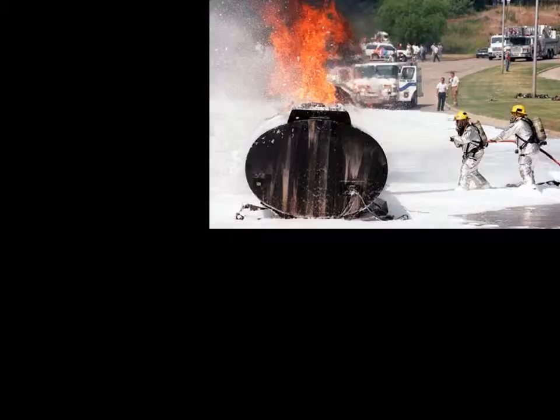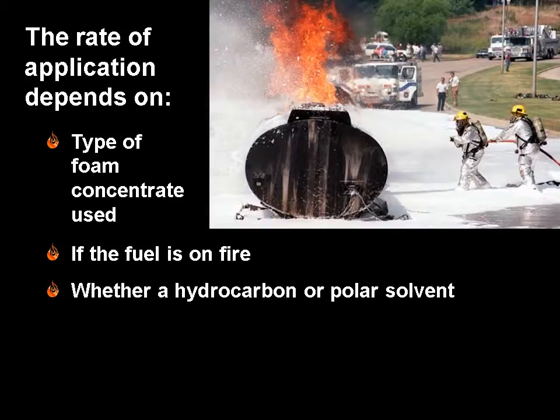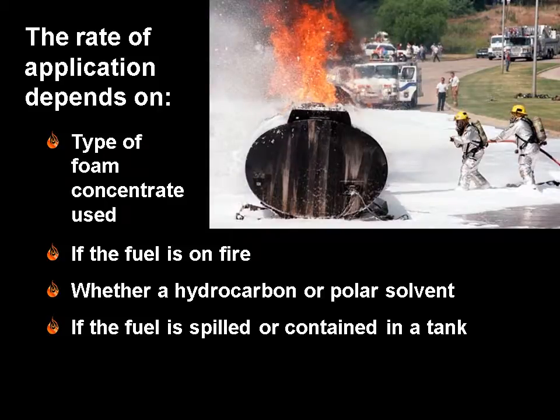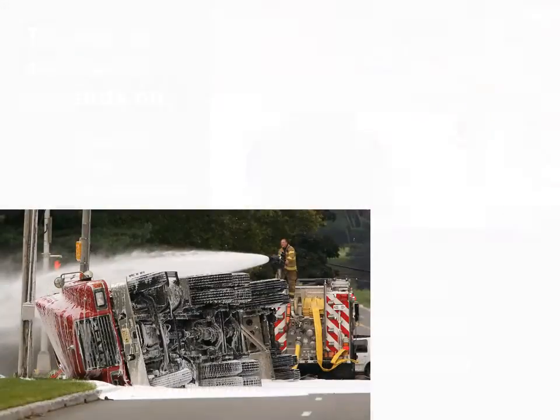The rate of application depends on the type of foam generator being used, whether or not the fuel is on fire, whether a hydrocarbon or polar solvent is involved, if the fuel is spilled or contained in a tank, and if the foam is applied by a fixed system or portable equipment. Unignited spills require less application than burning spills. Heat and thermal draft do not attack the finished foam.